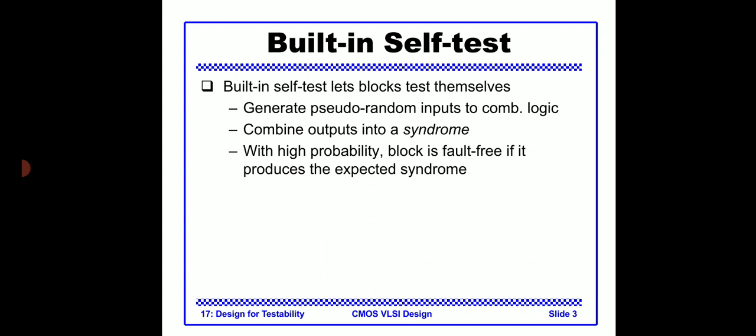The major components present in built-in self-test are the hardware pattern generator, test controller, output response comparator, ROM and comparator. Examples of pattern generators are stored patterns, counters and linear feedback shift registers, which are used for the stored responses. This also compacts and analyzes the test responses to determine the correctness of the circuit. Based on the responses during testing, the circuit is checked automatically, which we call built-in self-test.